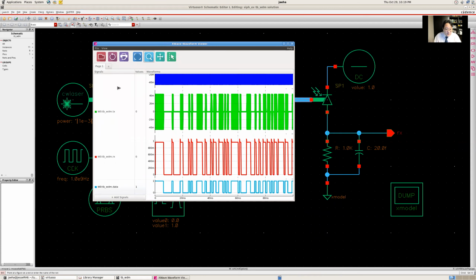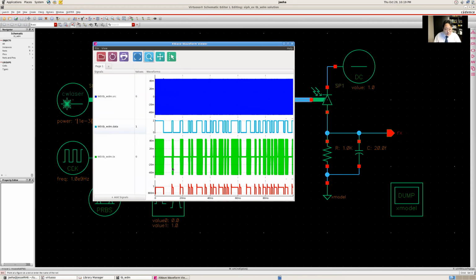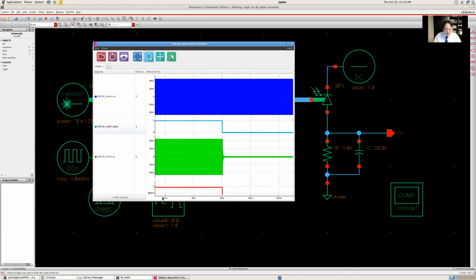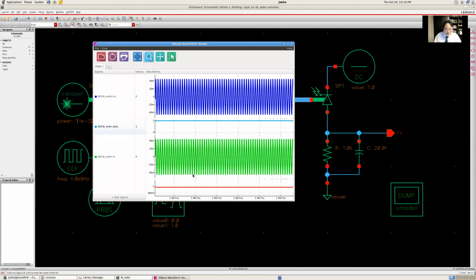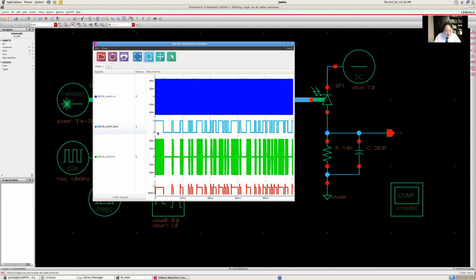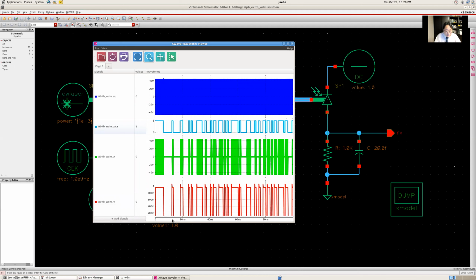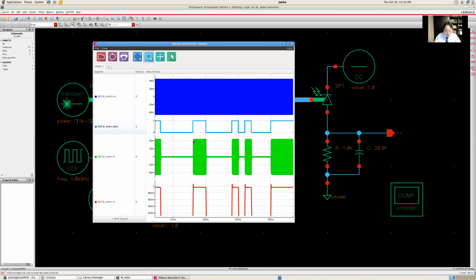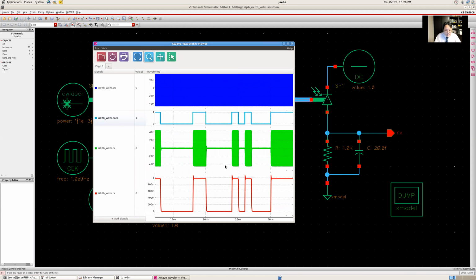So first we're sending a continuous wave laser, which is like a fixed frequency sinusoid. I have to zoom in a lot to see its actual sinusoid because it's, again, a 200 terahertz signal. And depending on this digital data, this ring modulator changes the amplitude of the optical signal. So sometimes you have an optical wave propagating, sometimes it's being blocked.